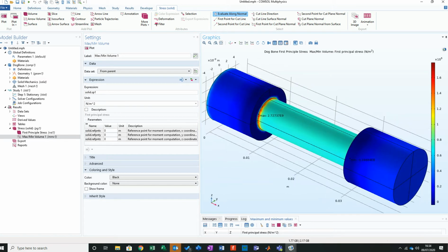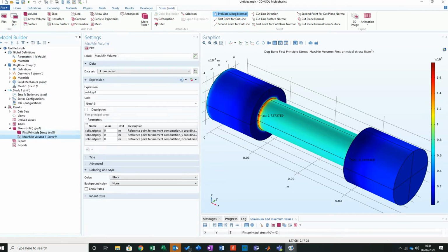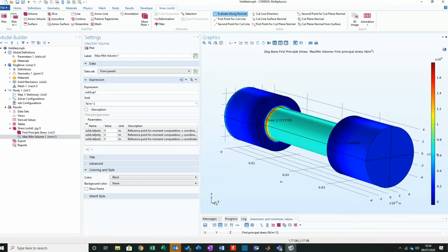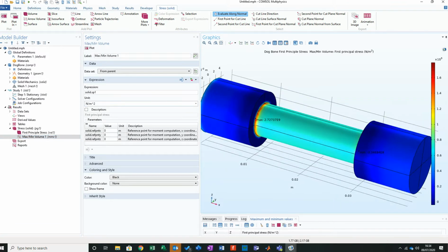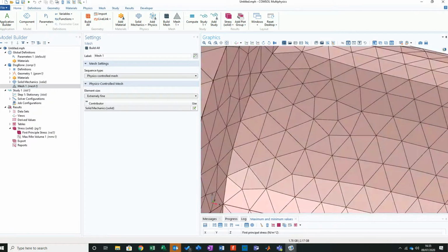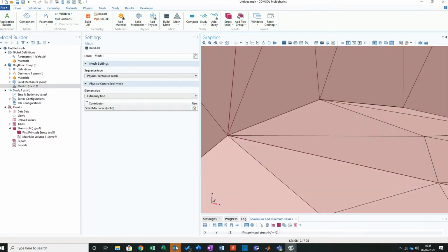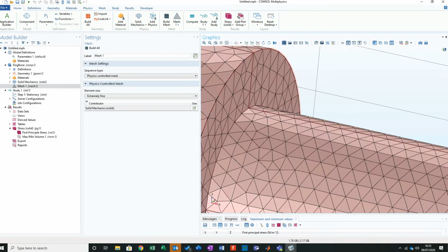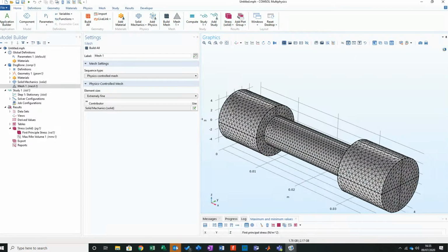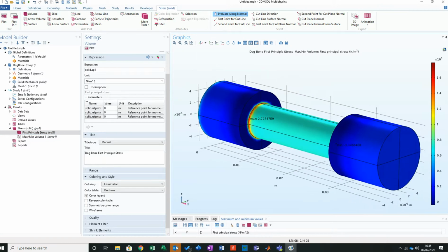Okay, so we're operating here at a max of 2.7. Or, I'm sure it was 2.5. We're a little bit out, but it's very confident. I would say our mesh is a bit naff for a start. That mesh is not a good representation. The concentration's around here. If we zoom into this particular area, look at the linearization around here. We could tidy that mesh up. I'm confident that that is moving in the right direction, and that's going to give me something that I can operate with. I'm quite happy with that.